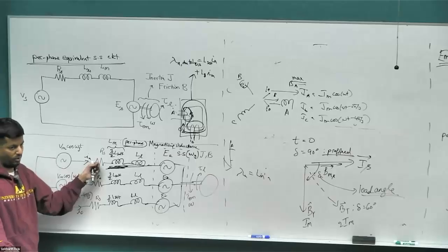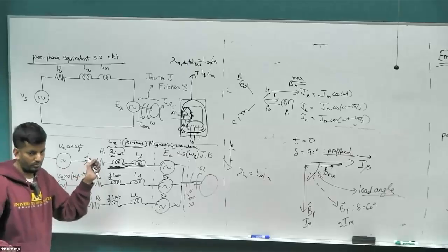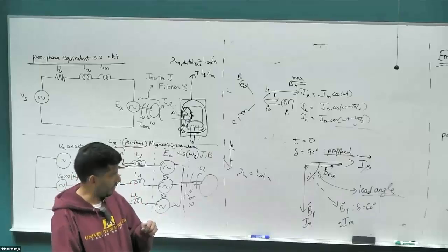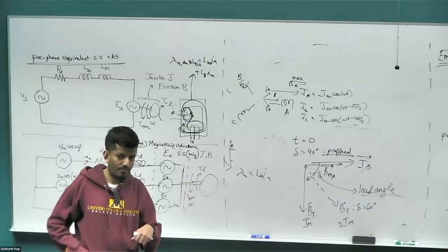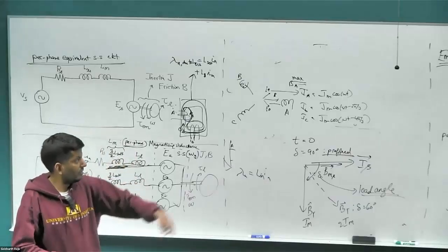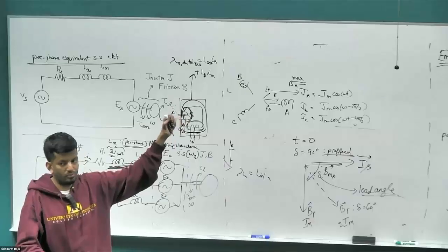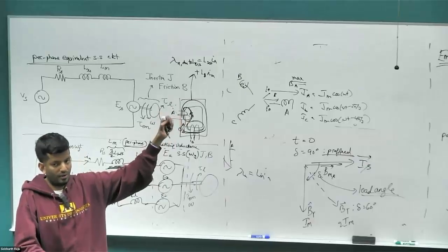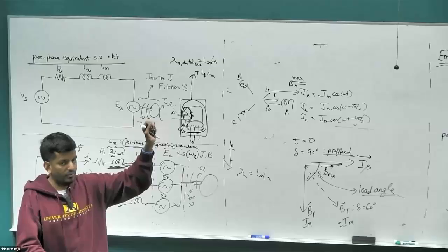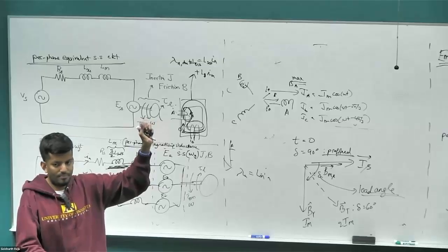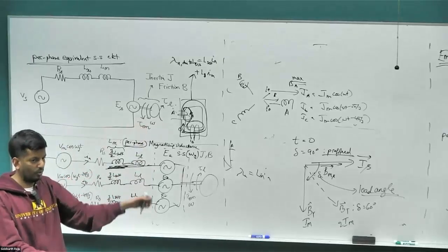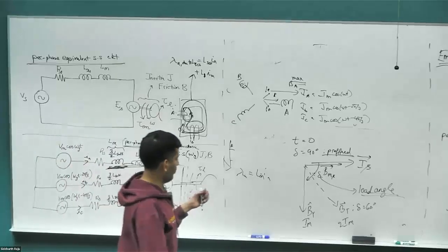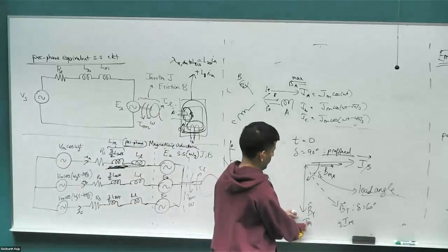Is that the only source of loss? If I put more current, what happens to the magnetic field in the air gap? B was mu naught N I times I divided by Lg. So if I increase current, magnetic field in the air gap increases. Why is it a problem? Saturation. So we end up with more hysteretic losses, right? We are doing a bigger loop on the BH curve. So that again would be a bigger problem. So you want to minimize this current as much as possible.